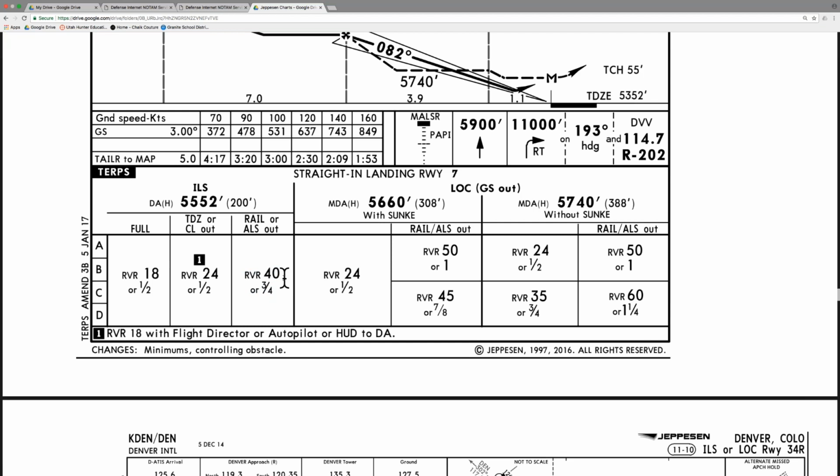They were all going to somewhere in the Chicago, Milwaukee area, and he listed Fort Wayne as the alternate for all of them. Well, if everything was working correctly, Fort Wayne's minimums would have allowed him to list it legally as an alternate. But the approach lighting system was out of service, and so that took his minimums higher and out of legal status. So he went from listing a legal alternate to an illegal alternate because the approach lighting system was out of service.